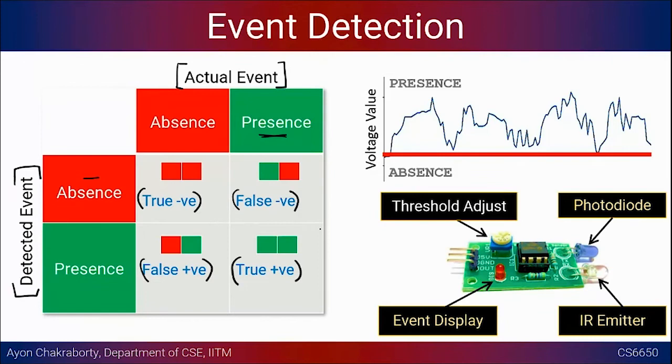In the sense of how far your obstacle is from the device, if you don't want to take any chances, even if you are one foot away from the wall, you might say there is an obstacle and you want to stop. You don't want to take any more risk. Whereas if you are operating in a very small area, maybe you can tolerate up to a few centimeters, maybe 5 centimeters. Within 5 centimeters, you want to report that there is an obstacle and you need to stop.